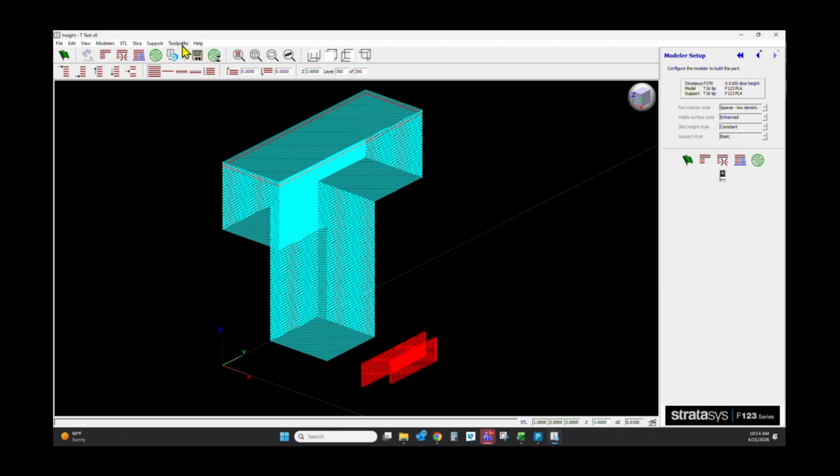So if I were to try to adjust my toolpaths here, you can see now that that option is completely grayed out. It is telling me you can't do anything to adjust this PLA toolpath setup. We can basically slice the part, generate toolpaths, and that's pretty much it. But we can override that once again using our custom groups.